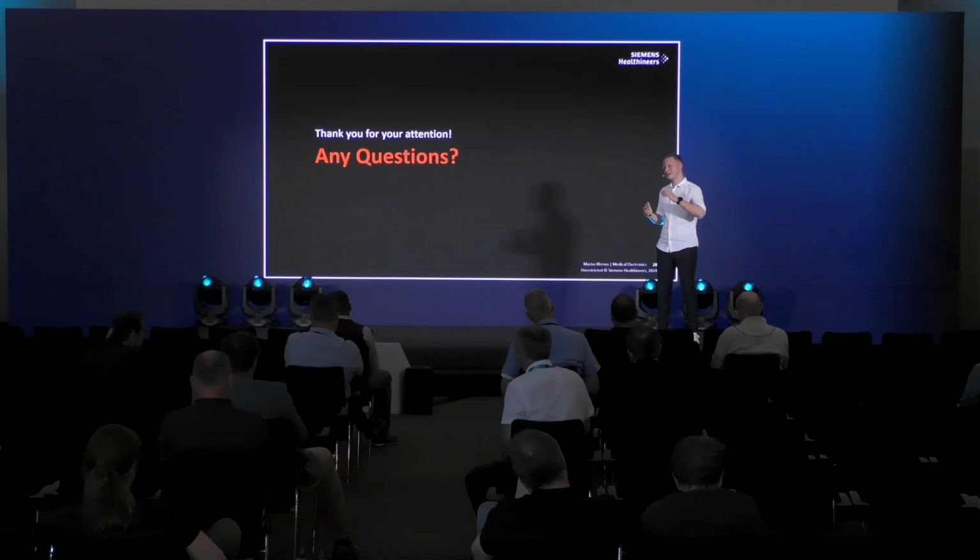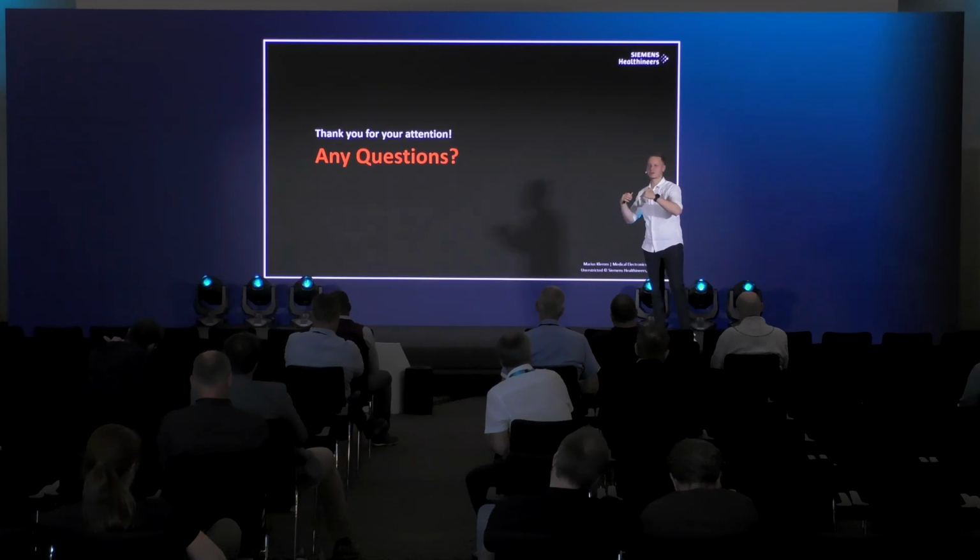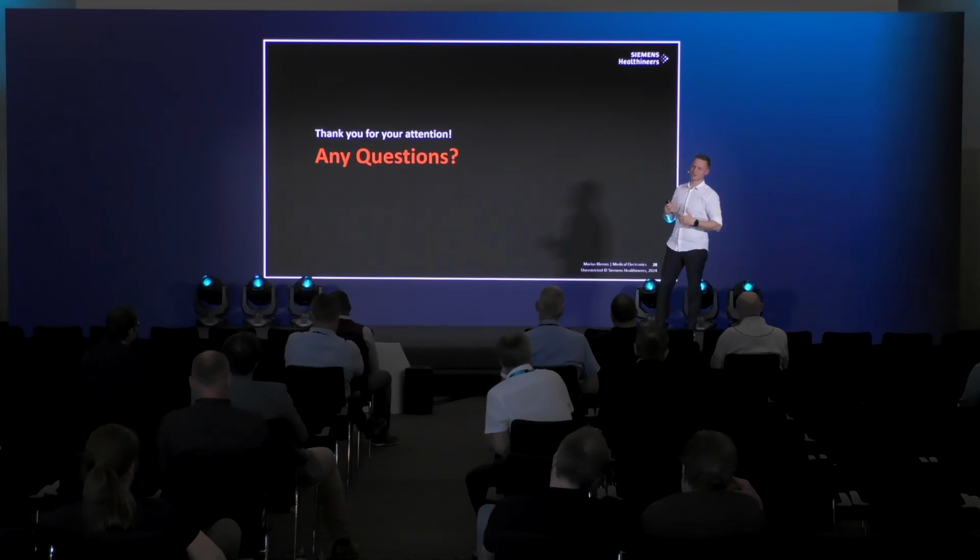We're not only trying to estimate the via impedance itself, but also the effect of the remaining stub, even if it's small: we're getting more capacitive loading and then reducing your impedance. So we always try to get a good approach with this, which is still applicable in PCB design.